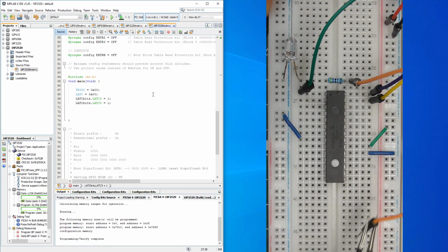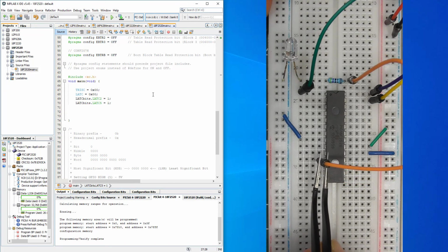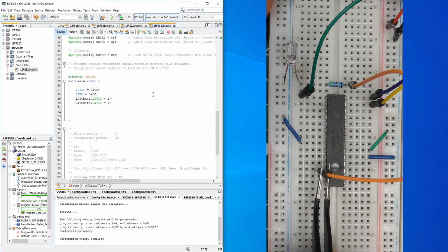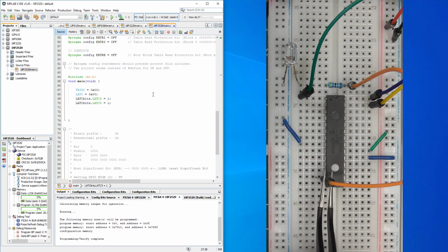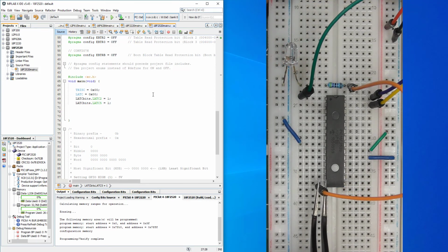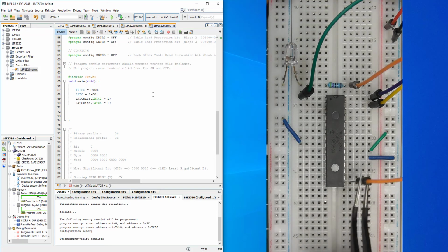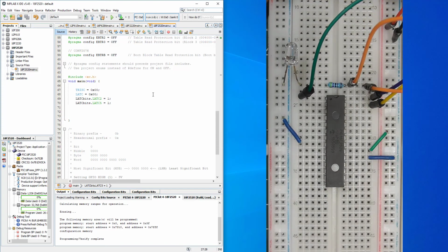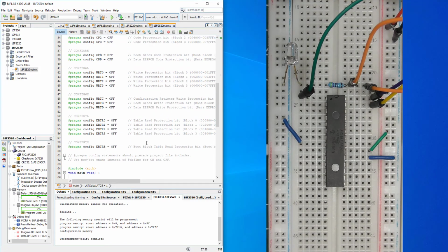Okay, so we count to the fourth pin, 1, 2, 3, 4, so we should have 0, RC1 0, now RC2 says 1. Okay, now RC3, sorry, 0, RC4 0, RC5 on, and the rest of them off. So the program works perfectly the same for both of the PICs, apart from the pin configuration.